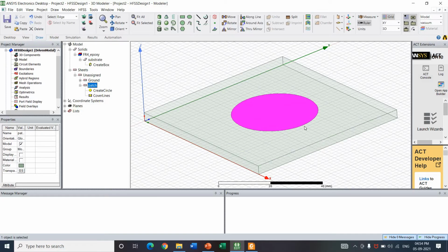So when I am directly connecting a line input at this point, definitely the reflection will take place here. Standing waves will be generated and reflection will take place. So what I have to do is cut a small portion in such a way that the input line, that is a transmission line, is inserted into this circle in order to match with a 50 ohm point. So this is an optimization that we have to do. We have done the optimization. I will give the final result.